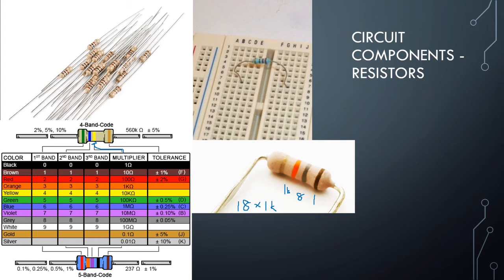Just make sure that you're using them, because if you use a resistor that is too low, you could burn out some components, and if you use one that is too high, the current will not be able to flow properly and your circuit will still not work.